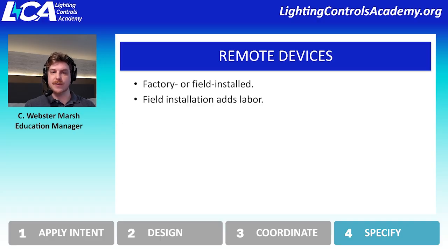But these field devices might be a power supply for a touchscreen, so you might need to have something located nearby the touchscreen that converts AC line voltage to DC low voltage, or you might just need additional devices to support another device's functionality. So getting an idea of what the remote devices are going to be, how they're going to be installed, will help clarify any additional requirements for that device and its functionality.